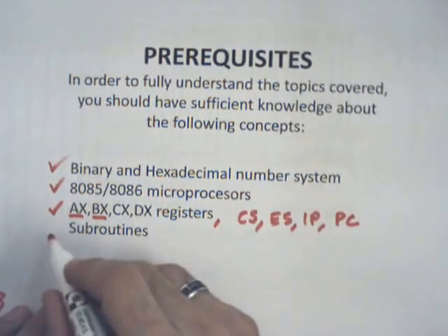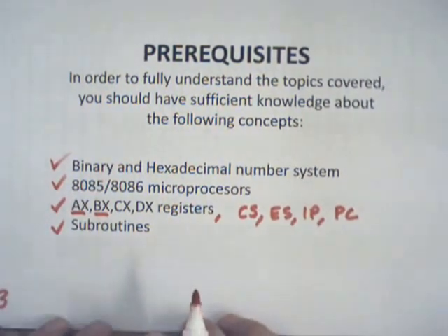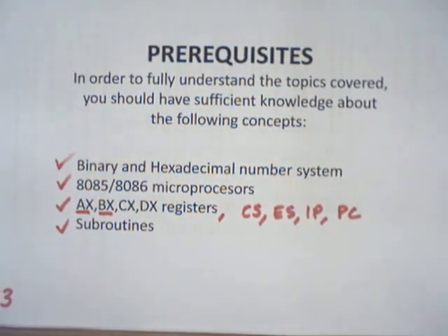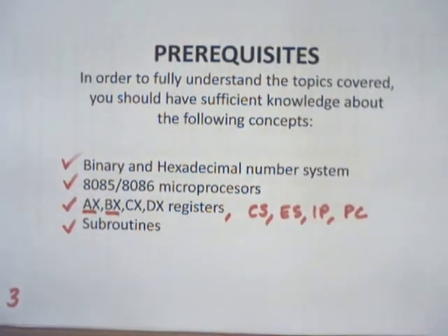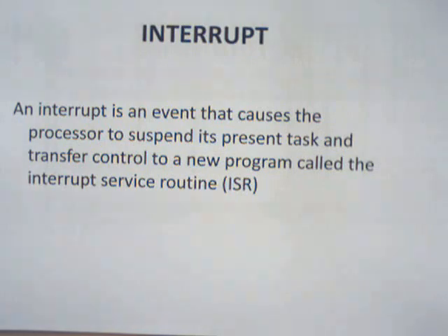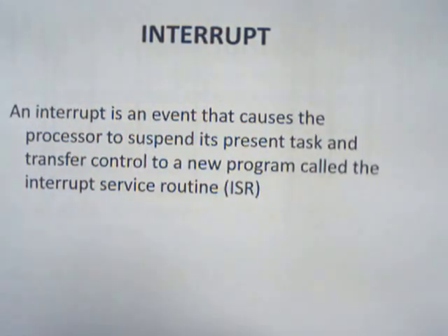As well, subroutines should also be studied before knowing details of the interrupts. What's the meaning of interrupt? In short, interrupt is an event that causes the processor to suspend its present task and then transfer control to a new program called interrupt service routine, ISR.